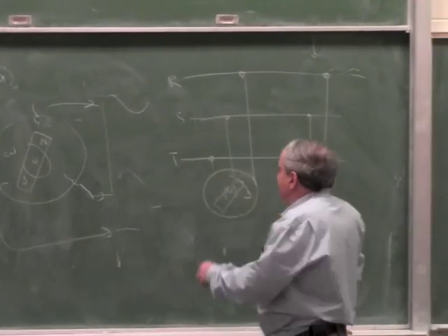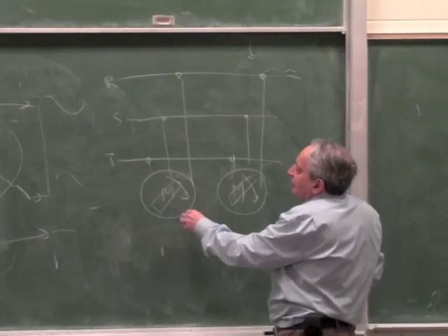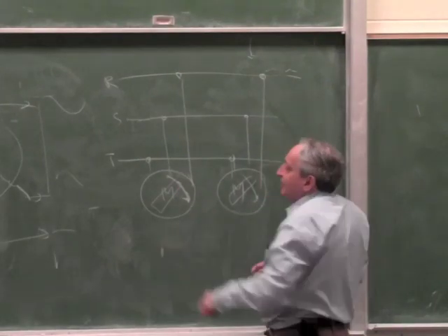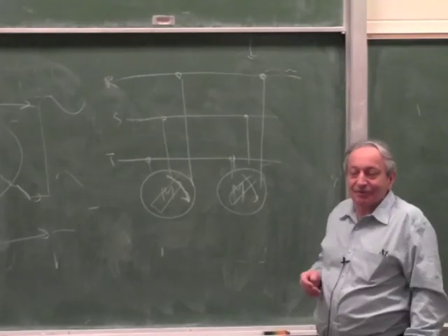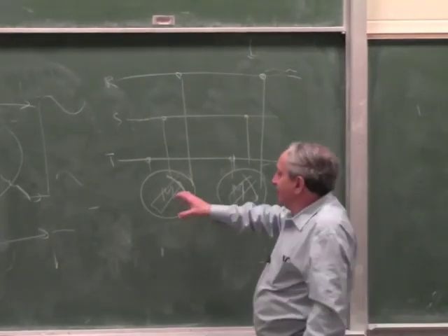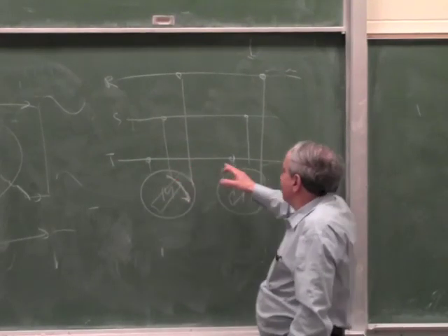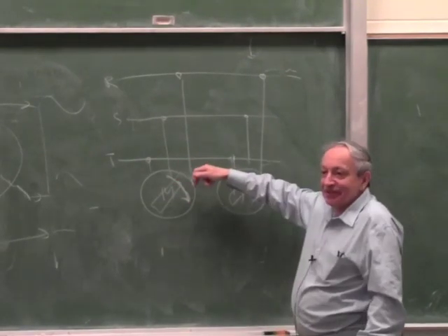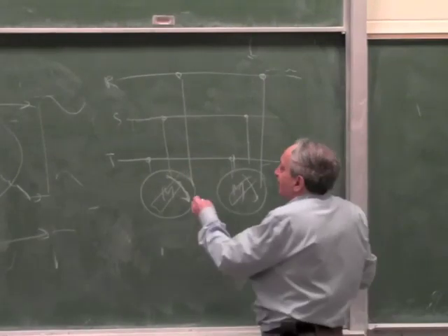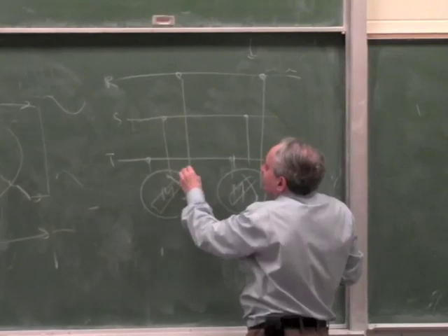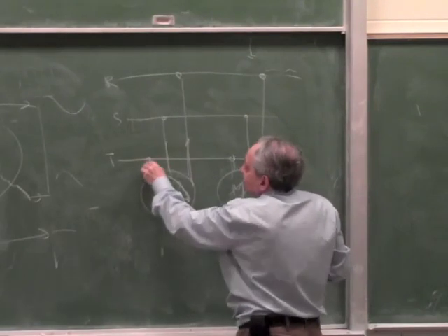Now what happens if you take this motor and not only take off the load, you are actually pushing it to try to make it rotate faster? It will induce a voltage which is a bit ahead in phase than the voltage which comes in, and because it's a little bit ahead in phase, instead of the currents flowing in, the currents will flow back.